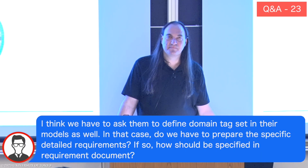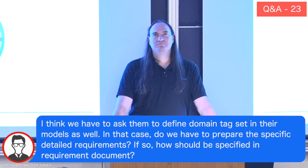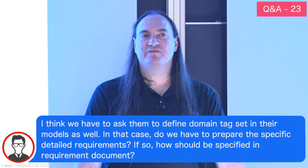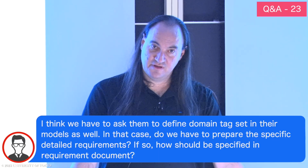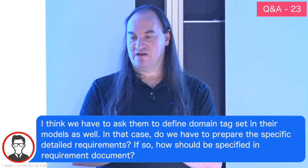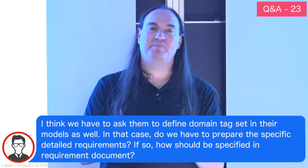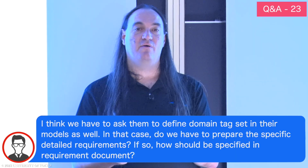Not sure I understood the question. Let me try to answer it and tell me if I did. Domain tag sets are almost like an alias or a symbol for surfaces. So I've defined that there may be a domain tag set called box baseplate. And so I can put surfaces into box baseplate later, but I could make contact to box baseplate now.